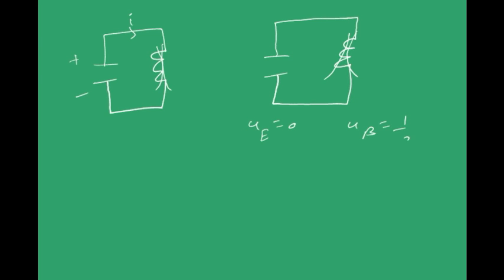So there comes a state where the capacitor is chargeless. All the charges have been transferred, and at that state there will be magnetic field lines inside the inductor. So the energy inside this capacitor is zero now, and the magnetic energy is half L Im square. So at this moment the current will be maximum. Are you getting me? Current will be Im.